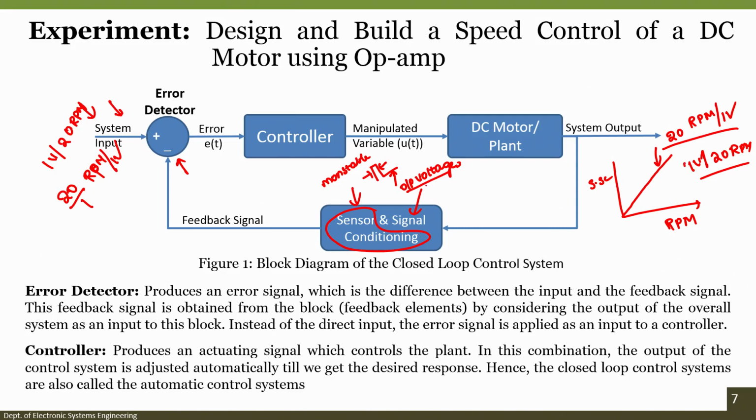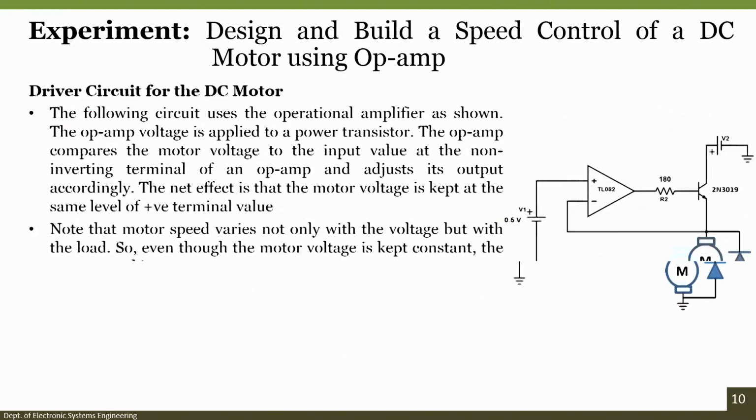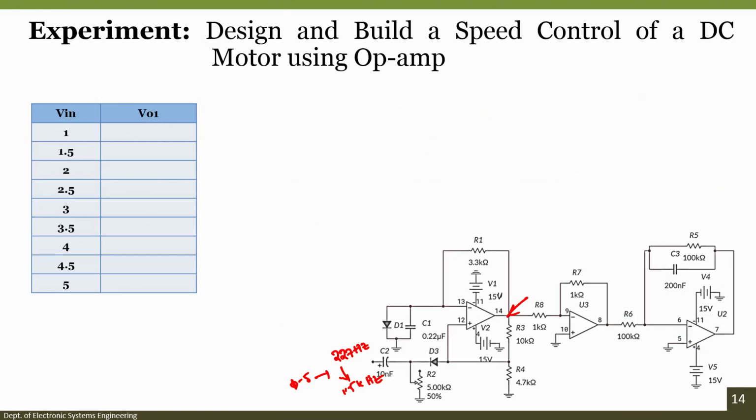Before this we have to get an output voltage, but how do we get a linearly varying output voltage? In order to do that, today we are going to integrate the output we get from the monostable multivibrator, but instead of directly connecting it to the integrator circuit, we connect it through an inverting amplifier. But why do we require an inverting amplifier?